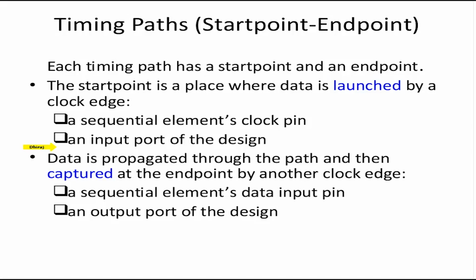So the timing tool, either Design Compiler or PT, will launch the data on one edge and expect the data to arrive at the second edge, still meeting the setup time window of the capture clock. So each timing path has a start point, which can either be an input port or the clock pin of the sequential element, where the data will be launched. On the next edge, the data will be captured at either the sequential element's data input pin or the output port.